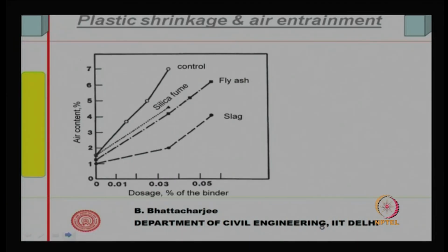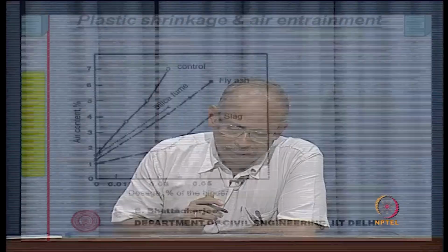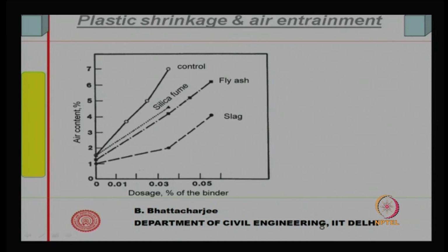If you look at plastic shrinkage, well, when we add water to the cement system and the cement paste is formed, it occupies somewhat less volume than the original overall volume. There can be certain shrinkage at the plastic state itself, and we can see that this gets reduced.